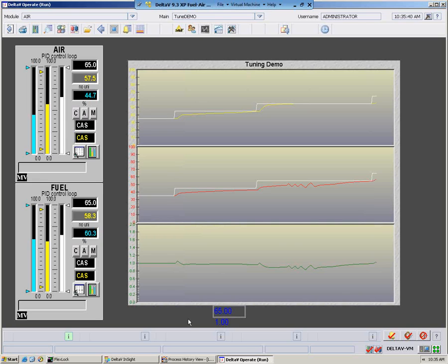And we've got our 10% increase in firing rate. As you can see this time around, our green line isn't nearly as drastic as far as its deviation on the fuel-to-air ratio. And the two curves are coming up together. But I noticed, Tom, that they're going up at the same rate. Yeah, you know, normally in a boiler application, folks out there are watching saying, Tom, we're going on an increase in load. I thought you said that the airflow is always going to lead, that the fuel flow is not going to go up until the airflow goes up. So why is our set point changing?